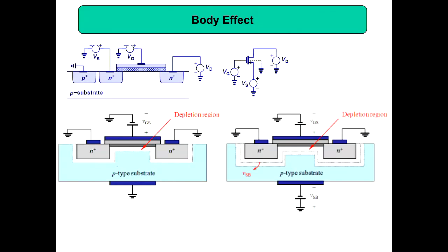Then sometimes people also connect some voltage here, some negative voltage. Why? Because they may want to control the width of this depletion region for some reason. When you control this width, you are also controlling the height of the channel here, not this width, the height. The height you can control a little bit. In that case, if they are doing like that, because here you can see more negative is connected, this is becoming more negative, reverse biased. So in that case, people will write maybe a negative voltage here. Then when you take into account body effect, because you are grounding the body or connecting a negative voltage, people will ask what is the effect? What we have to look into?